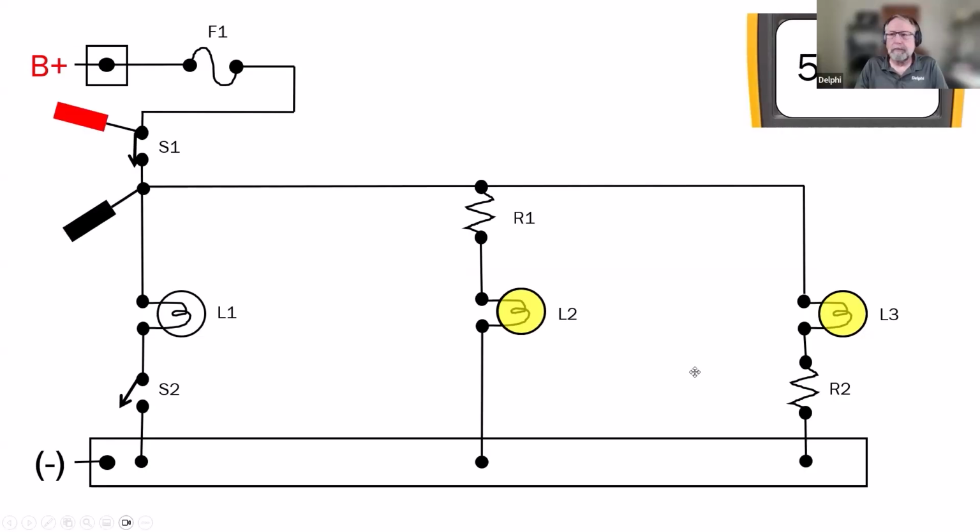Let's measure the switch. 5 millivolts. Is that a problem? Not by any means. Nothing wrong with that. The conductor leading from the switch down to R1, and you're seeing 2.3 millivolts. Is there a problem there? It's here where we take this measurement, and now we see that we have a voltage drop of close to 9 volts. This is a ridiculous example in the sense that if there was actually a 9-volt drop taking place there, you'd be generating an enormous amount of heat, and you'd probably figure out pretty quick what was wrong because there'd be a fire. It's probably how that would go.